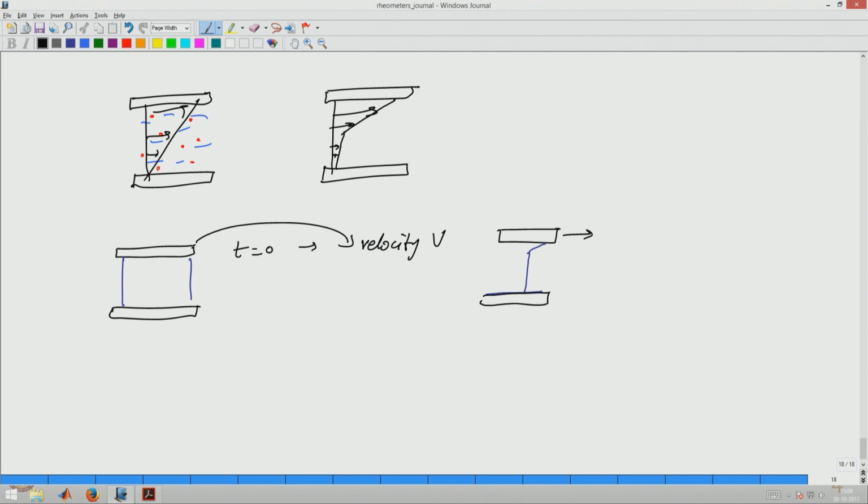So, that is the difference, but again at the steady state, what you would see generally, provided the shear stress that is being applied is higher than the yield stress, is again a linear velocity profile. But how do you know that it fully flows? That depends on the velocity with which you are applying, and therefore, the stress being